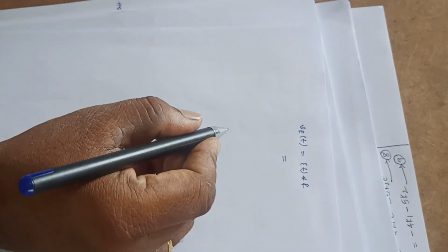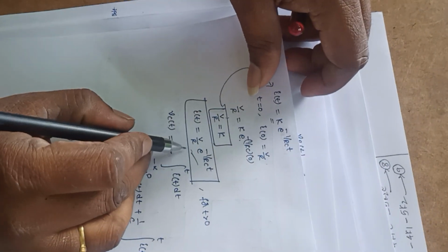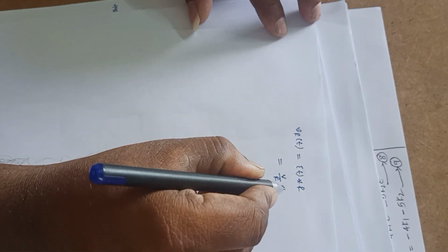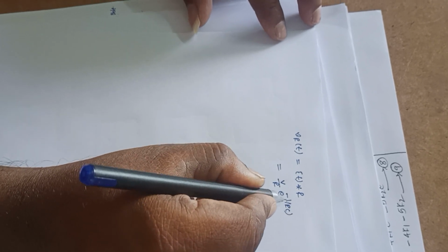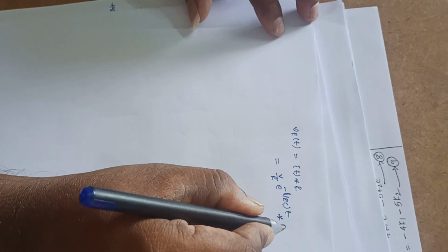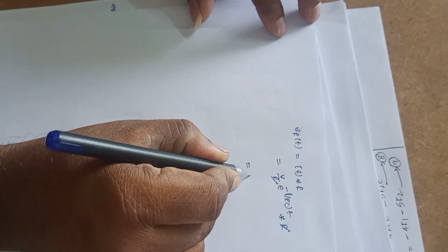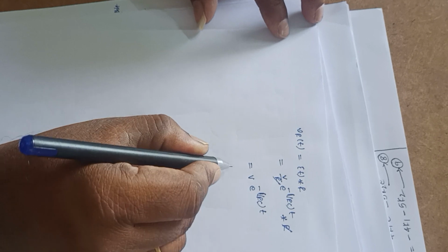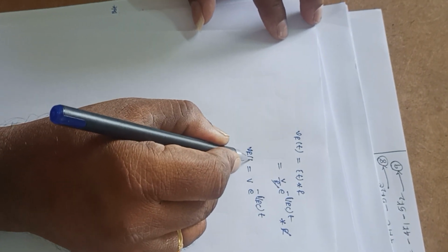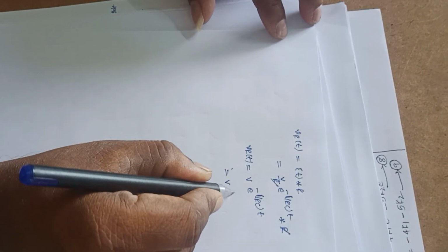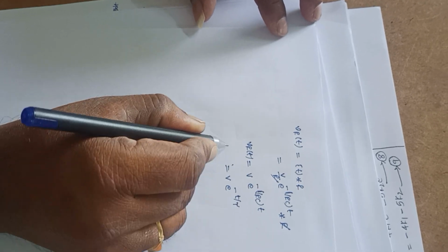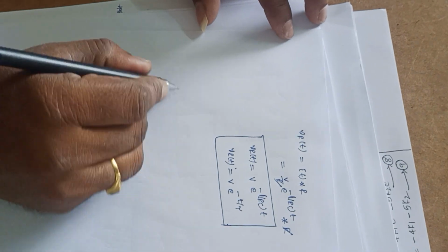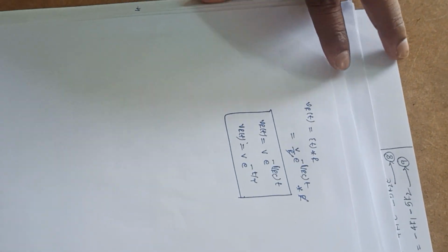So I of t, just now we calculated, is equal to V by R into e power minus 1 by RC into t. So it is V by R into e power minus 1 by RC into t into resistance. Resistance will get cancelled here. So V into e power minus 1 by RC into t, that is Vr of t, or we can also write it as V into e power minus t by tau. So this expression is the voltage across the resistance Vr of t.